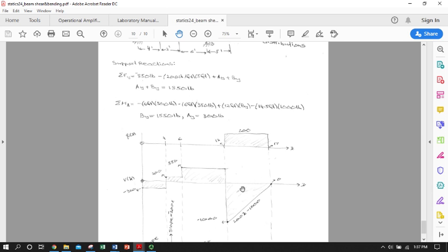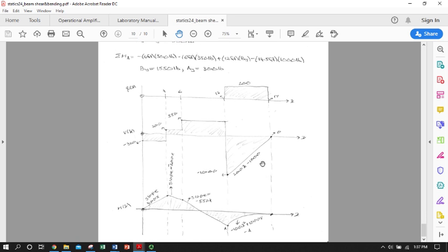And that's locally defined, not defined with respect to the origin. But we do know it's a line equation that ends at 0. So if we want to look at the corresponding moment without going through a whole lot of calculus, we could use the relationship between M and V and know that, well, okay, if Q is basically the slope of V, V is the slope of M.